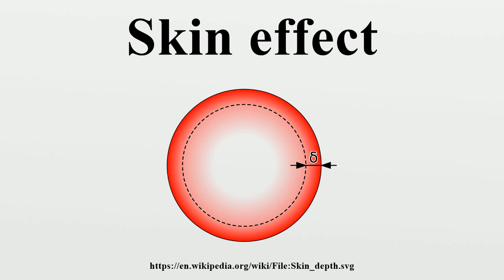As the skin effect increases, the currents are concentrated near the outside of the inner conductor and the inside of the shield. Since there is essentially no current deeper in the inner conductor, there is no magnetic field beneath the surface of the inner conductor.